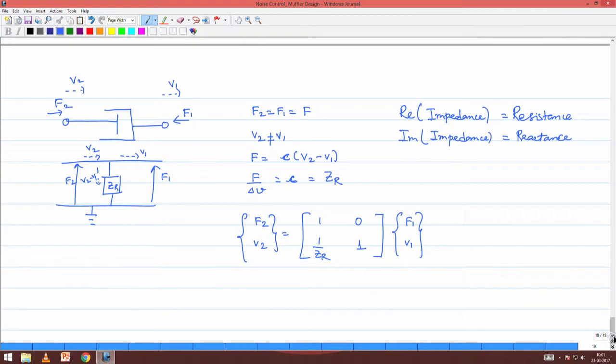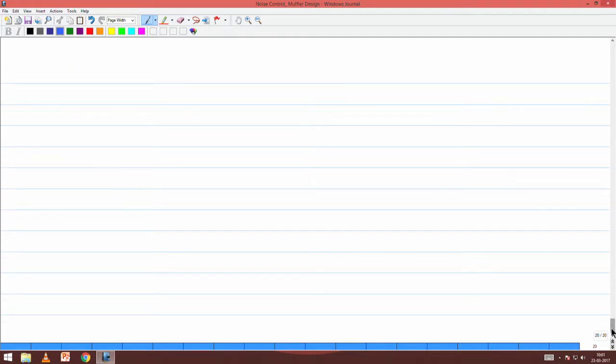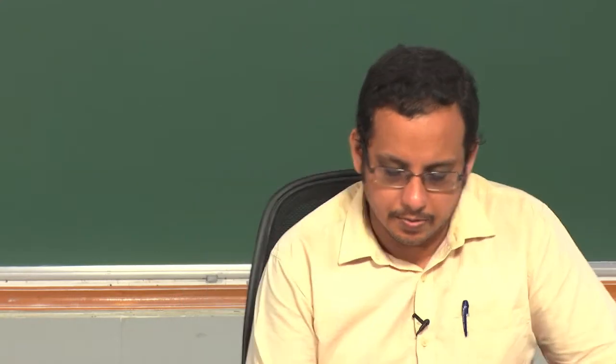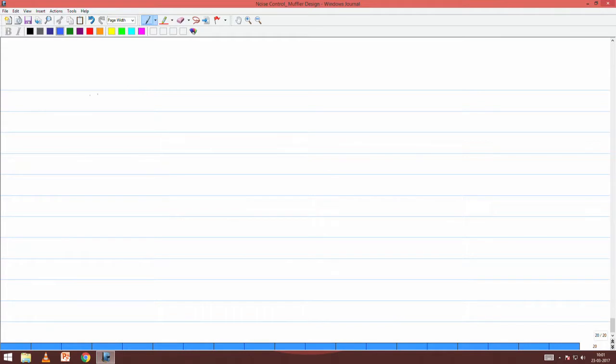Today we will look at how to assemble these fundamental elements that were derived, and using these assemblies of springs, masses and dampers, we should be able to construct any mechanical system. Accordingly we will define the electrical analogous circuit for this, and we will also find out the transfer matrix appropriate to assemblages of such spring, mass and damper elements. So, what we will do firstly is start with our very fundamental example of just a spring and a mass.